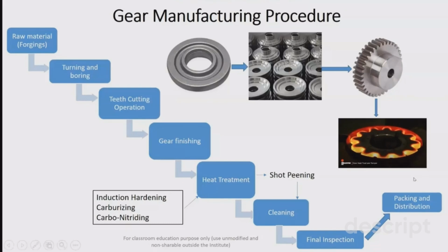Some carbon deposits, oil, dust and grease can also be deposited on the surface. The gears should be cleaned thoroughly with the help of some cleaning agents. Solvents and detergents are available in the industries, and then you can clean them and have the final inspection in terms of the number of teeth which you have cut and what the error in the profile is, which you decided in the designing stage.